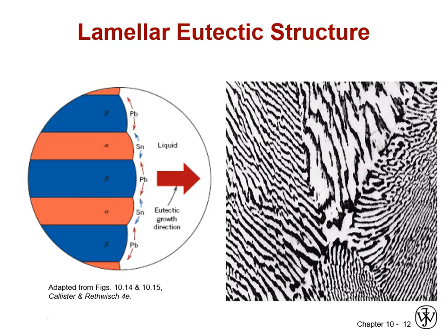Or for in-service properties, if one were to use a cored microstructure in high temperature service, we certainly wouldn't get the properties we would expect from the average. So there's an example of when diffusion does not keep up.